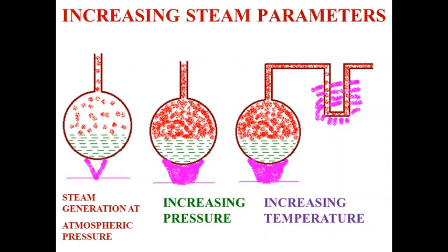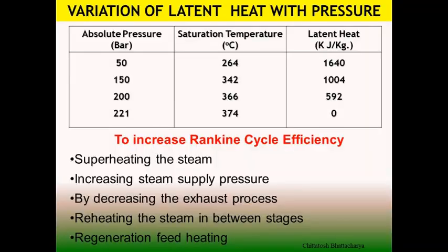So we have to see how we arrange the heat addition successively so that the tube metal temperature does not get higher and damage the tube by high temperature oxidation.